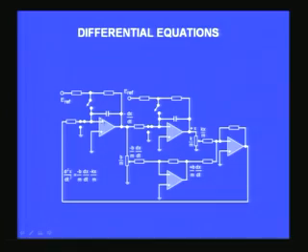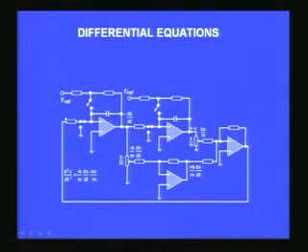integrators. Integrators are much simpler to work with than differentiators. I already mentioned to you, you may get into problems of noise when you introduce a differentiator. Therefore it is always preferred to use the integrator. So you use an integrator, assume that d square x by dt square is available at the input, then you can integrate it to get dx by dt at the output. You again integrate it using this circuit and you get x.